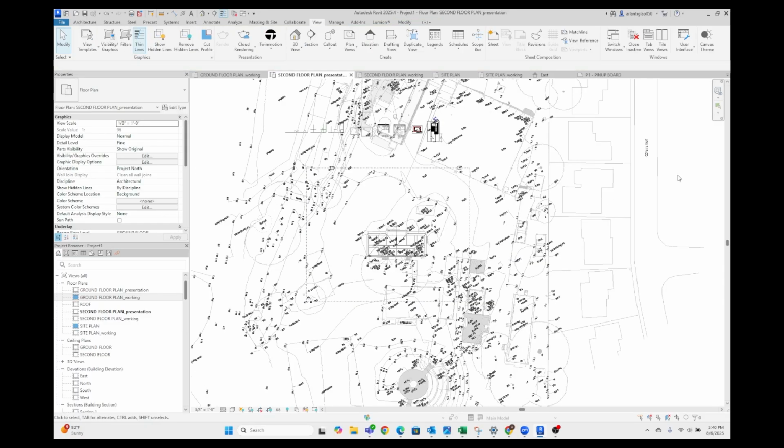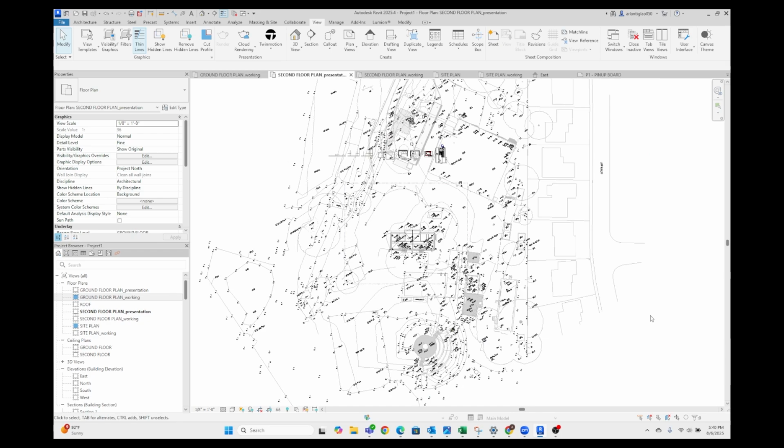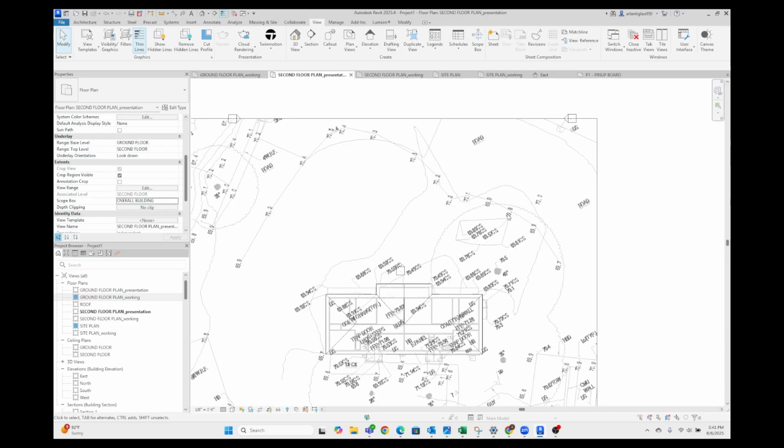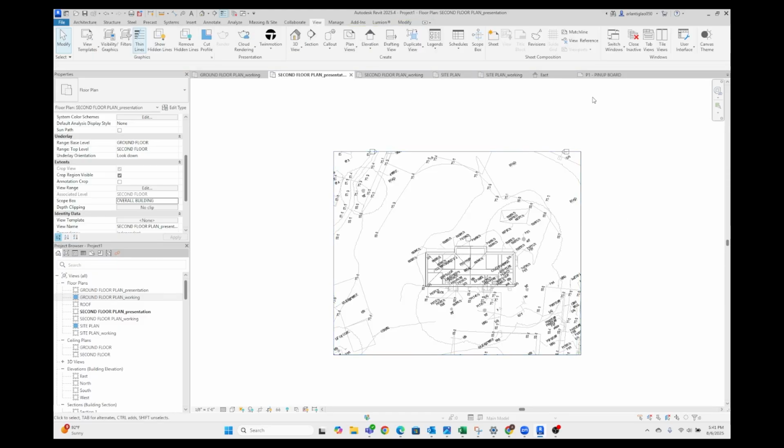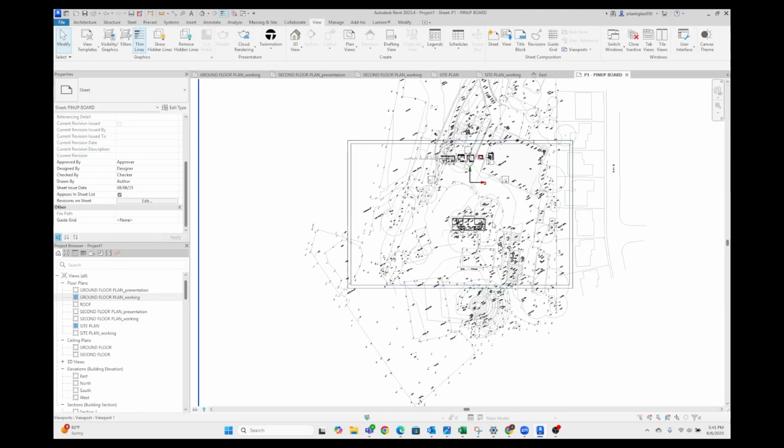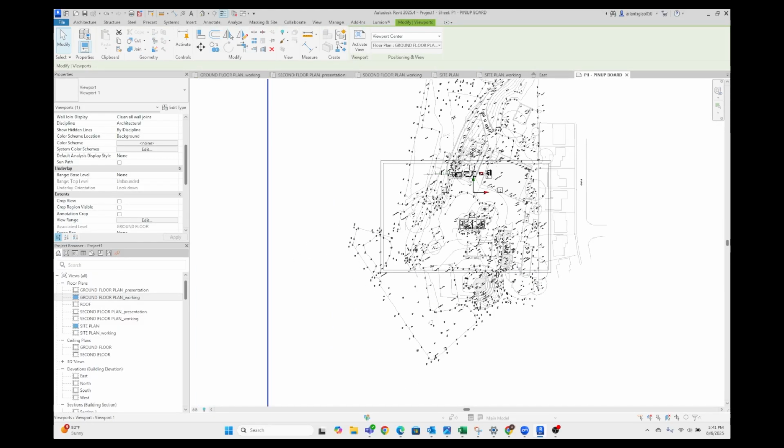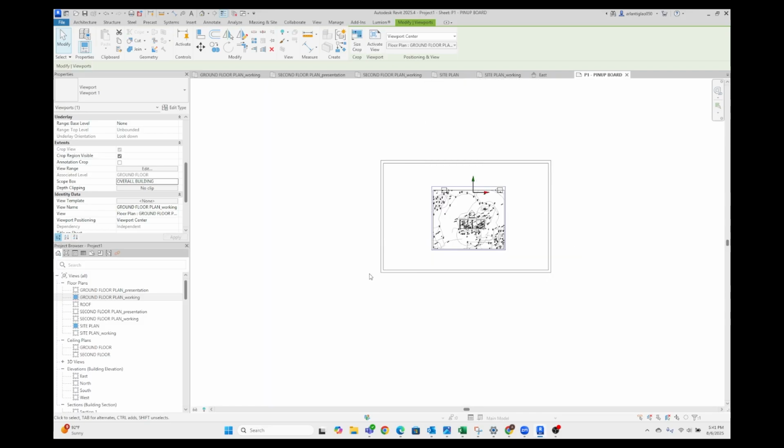And yeah. So now if we go back into our general view in Revit and scroll down to like Extents and click this scope box tab, we can click on the box that we just made, which is Overall Building, and it crops it down to this box. And now when I go back into my sheet, I can click on the view again, assign it a scope box, which is Overall Building, and there you go.